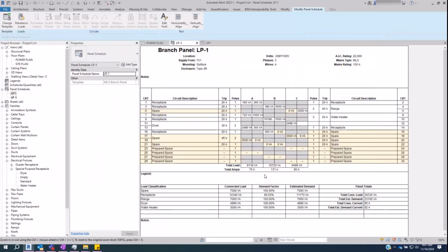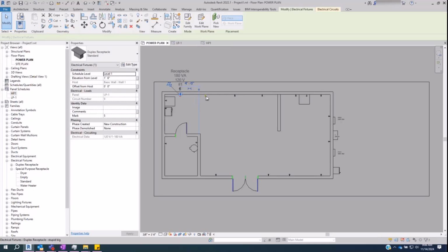The contractor will like you a lot more, because in normal stuff you would have everything drastically oversized, like the conductors, the panels, and so on. You'd be saving the client money if you actually did the derates. The best way to go about that is to default to NEC every single time. And if you can't, that's where your engineering judgment comes into play. If you had to stand in front of a jury of 12, looking at a widow, trying to explain why you did something that got her husband killed, can you justify that idea?